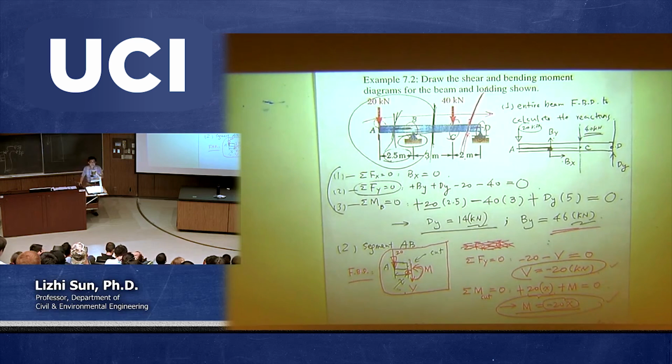So typically, we solve this kind of beam problem in steps. Number 1, we always need to look at the entire structure and plot the free body diagram for the entire structure in order to determine those reactions, because reactions are forces applied on the beam as well. It just doesn't matter how we're going to calculate, right? So look at this one. We have this beam with the 2 forces given with magnitude, but there must be another force acting on point B. We just do not know the magnitude.